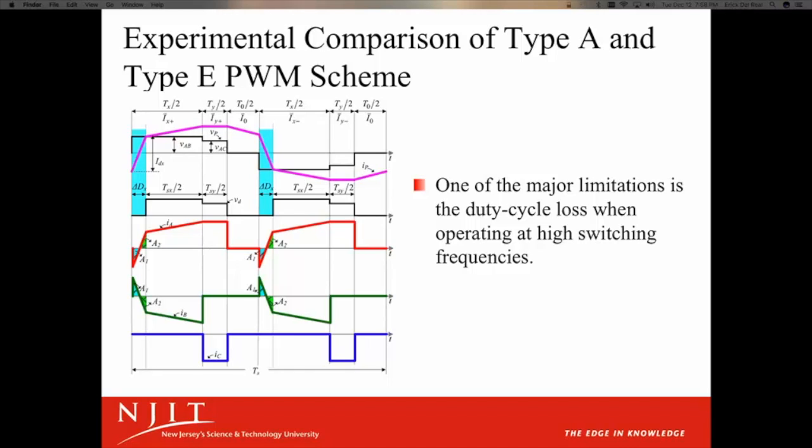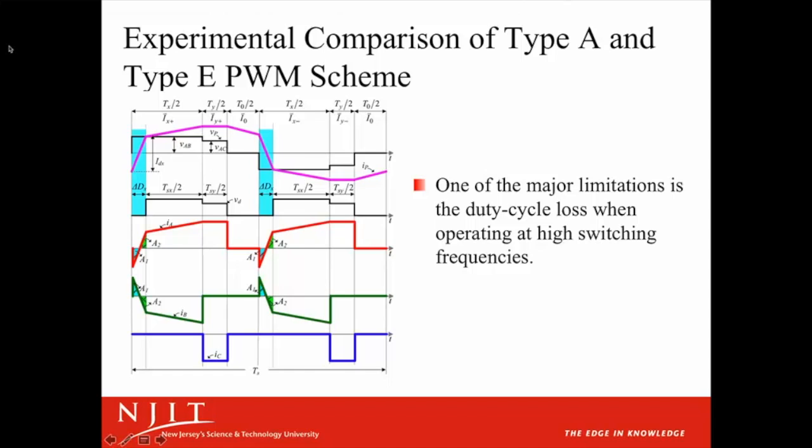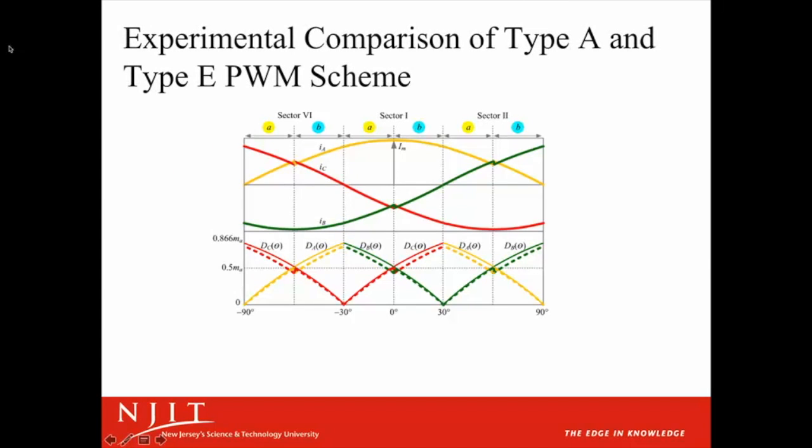The output voltage ripple as well as the input THD is affected by the loss of duty cycle. If the applied duty cycle is not compensated enough, then let me show the next one. And this is what they're trying to show right here. When the duty cycle is not compensated, then we're going to inherit more loss of duty of output voltage. Sorry about that.